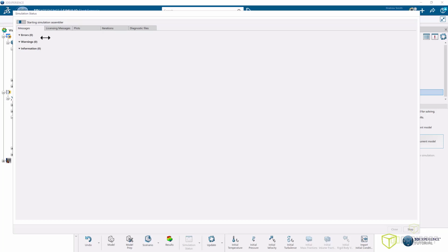A lot of times we'll have errors that say, for example, you have 2 meshes, can't solve. Another one, or warnings, are going to be stuff like this: variable heat flow was not found. I have no heat transfer here, so there's no heat flowing. So this variable is not available, and this is letting me know. And same with bad cell. Bad cell would be identifying my mesh, how it was not refined enough in some spots, or if I have a high aspect ratio of some of my elements. This will let me know about that too.